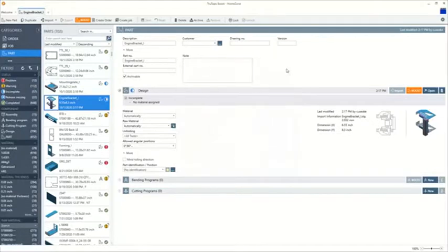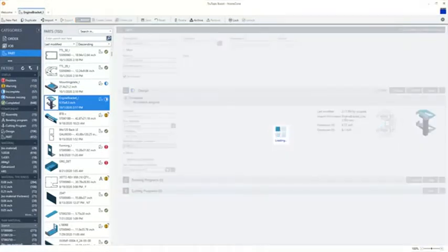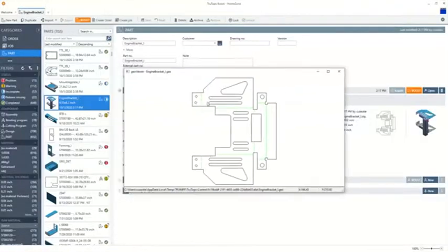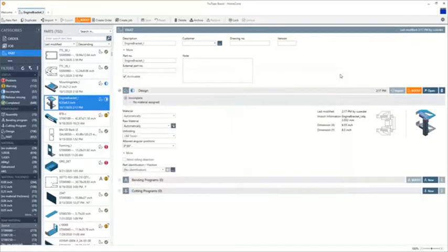If it passes the sheet metal validity test, it automatically flattens the model, adds bend line data, which are these green lines. And these green lines house information like whether it's an up bend, a down bend, and what angle needs to be bent, along with the radius of the flange that was existing in the model.